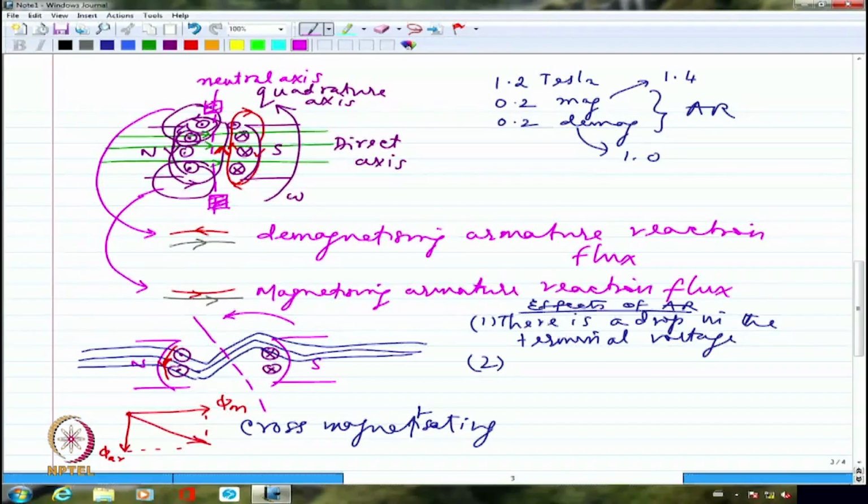It looks as though it is somewhere to one side. So the actual current transfer, which we call commutation, is going to face some trouble because of this. Previously, I had them exactly on the neutral axis, so I would not have any difficulty transferring the current from plus to minus or minus to plus. No problem.